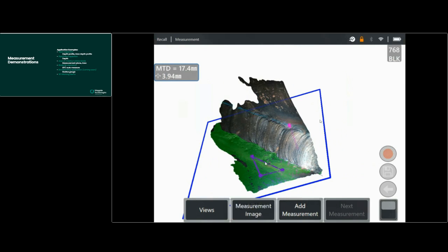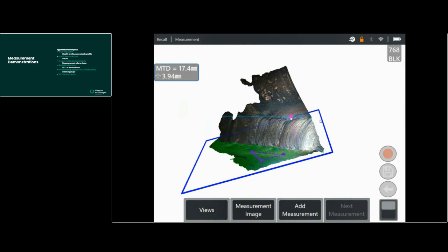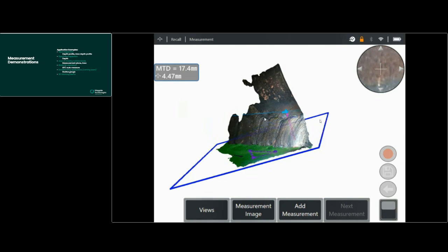If we go back to the full image, here we're determining the height of the weld. You might see on your screen the blue 3D surface mask that corresponds to all of the points on this image that correspond to this same distance, 3.94 millimeters. Here's a good example where you can adjust the position of that cursor so that you're including all of the irregularities of this weld bead. I'm just fine-tuning the position. You can see as I move, it's making good use of that projection of the blue surface.